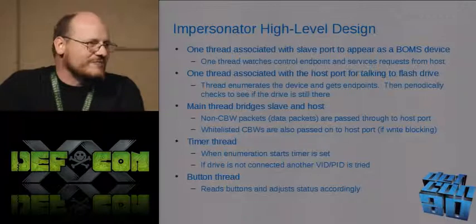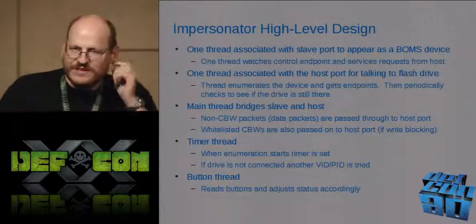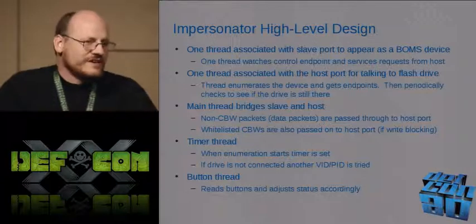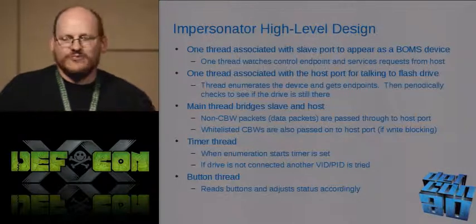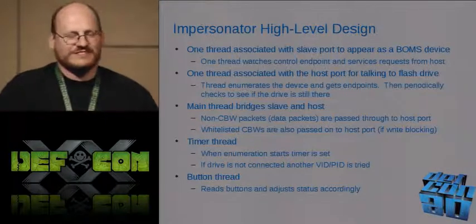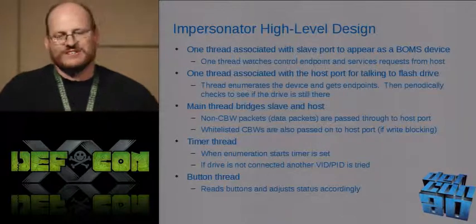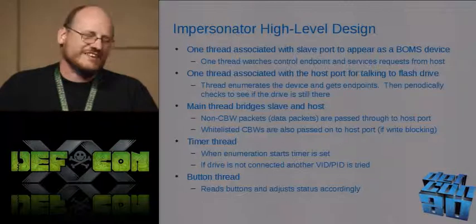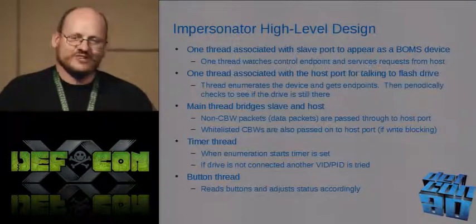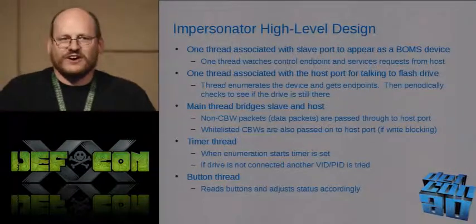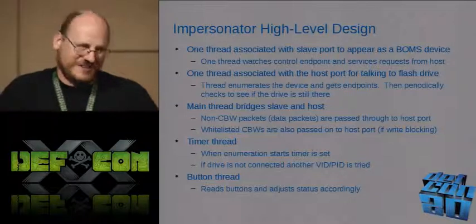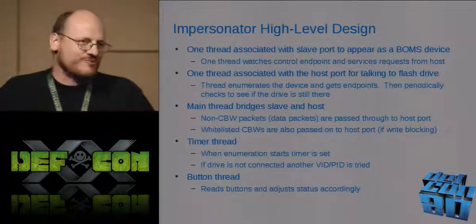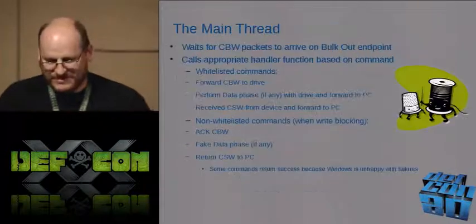Also, there's a timer thread, and what the timer thread does is if you're in the automatic mode, whenever the PC asks for a device descriptor, it says, oh, someone's trying to talk to me, and it starts a timer. If they stop talking to you after a second and they don't ask for additional descriptors, it says, oh, someone's blocking me. I'll go to the next one. And that's how that works. And there's also a thread for reading the buttons that come in.